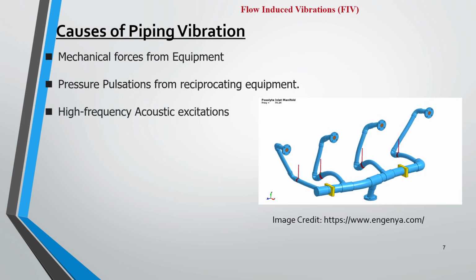Then high frequency acoustic excitations. High frequency acoustic excitations are generated by high pressure drops at relief valves, control valves, or orifice plates. It is mainly associated with pipes or pipelines that are transporting gas. It is normally not found in liquid systems.